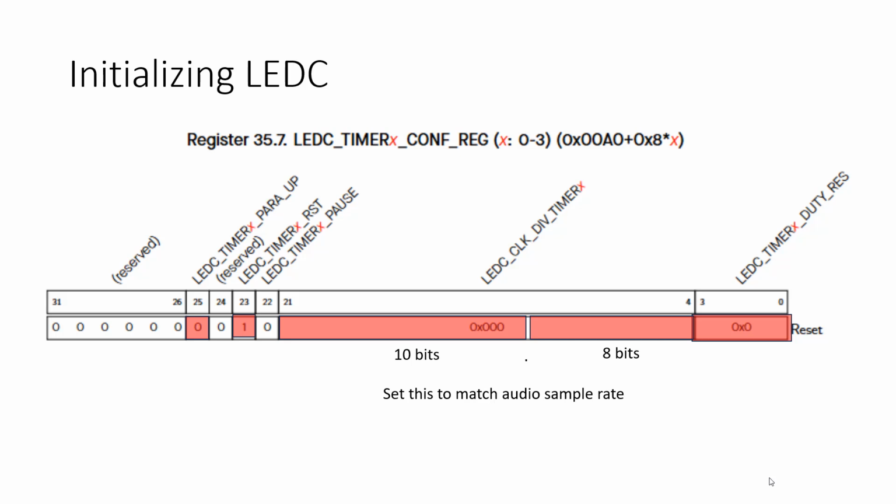But within that PWM period, the hardware is dividing that up into segments. It's subdividing each PWM period into its own clock, where it's counting for each PWM period. It has to count. Why? Because that's how it calculates the duty cycle, right?